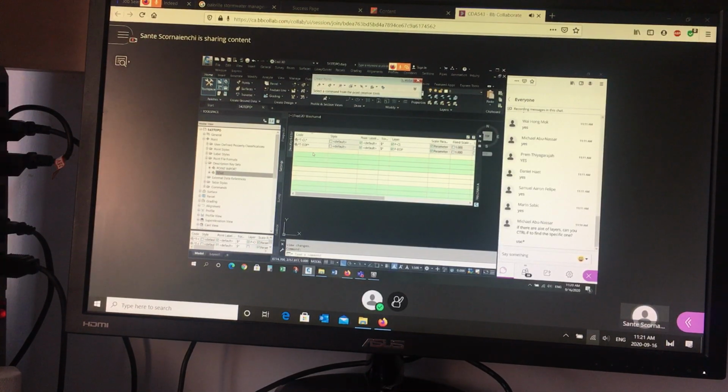Last thing you want to do is make sure that the style and the point label style, these 2 things, are on. For style, make sure they're on. For point label style, make sure they're on, set to default. I'll talk more about what that does and what that means when we get into point groups. So stay tuned for that.